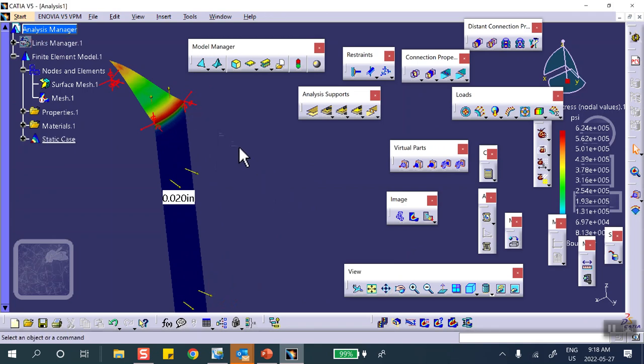It tells you that in this particular problem, the biggest stress is around the seam up there, and I agree. If it fails, in all likelihood, it's going to be at those welds. But do not take these numbers for granted, because the critical area, one critical area is on the top, I understand, but to get good stress distribution with shell elements on that top is not going to be possible.